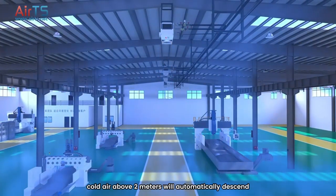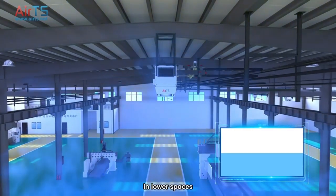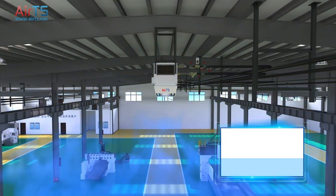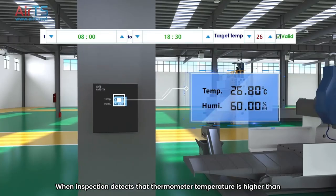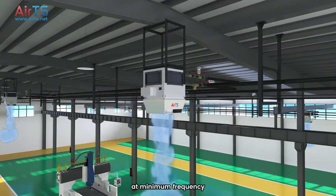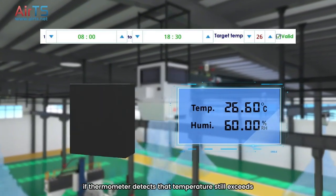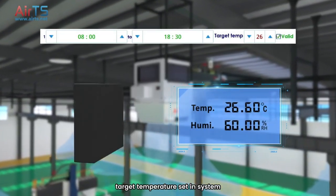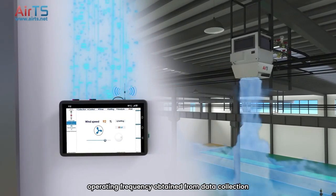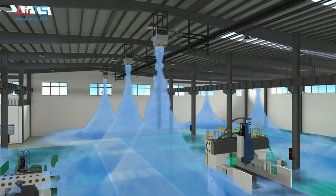During this time, cold air above 2 meters will automatically descend to compensate for cooling consumption in lower spaces. This process will continue for a certain period to effectively utilize excess cold air. When inspection detects that thermometer temperature is higher than target temperature set in system, device will automatically start up and run at minimum frequency. After running at minimum frequency for a certain period of time, if thermometer detects that temperature still exceeds target temperature set in system, then real-time commands are sent to increase fan speed based on current device operating frequency obtained from data collection, increase device airflow, and enhance output cooling capacity.